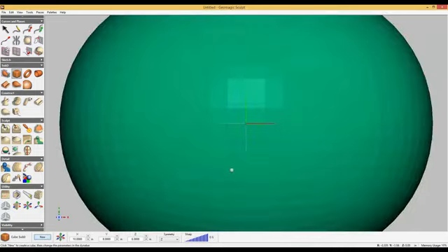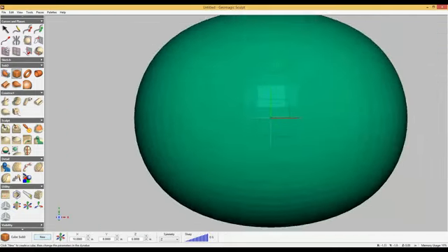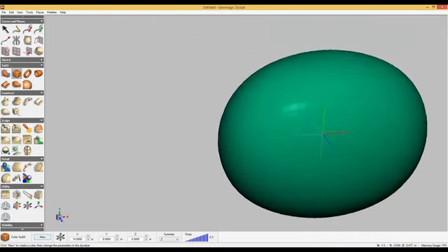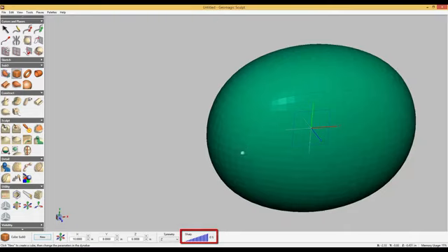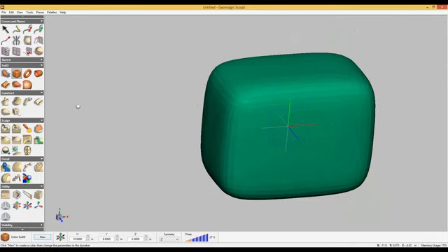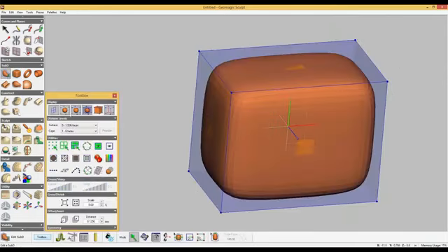Zoom out and rotate. Back on the Dynabar, change the sharp setting to 27%. Zoom out. To start changing and refining the shape, click on the Edit Sub-D tool. The Sub-D toolbox opens. Check the cage setting. Option 1 for 6 faces.